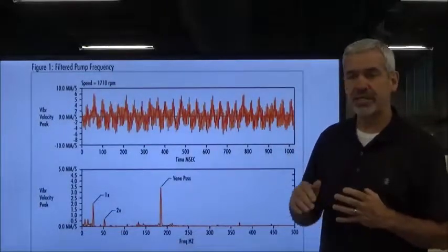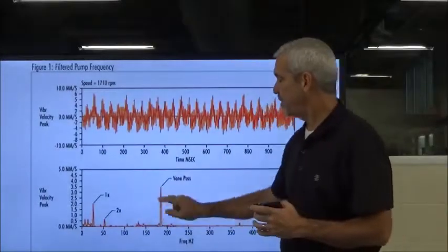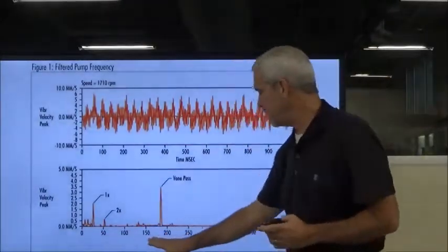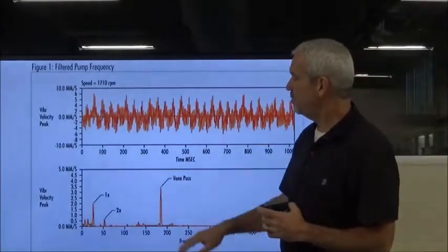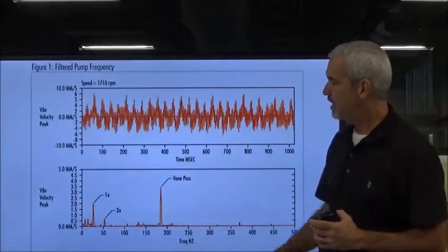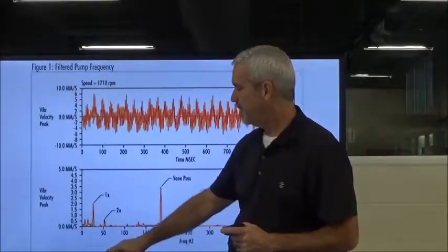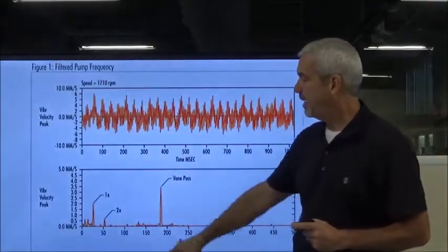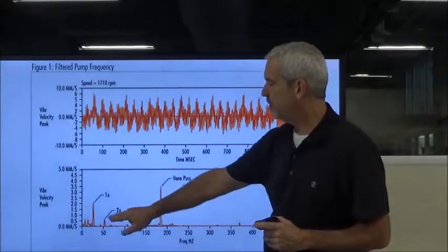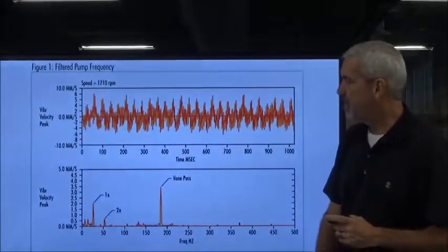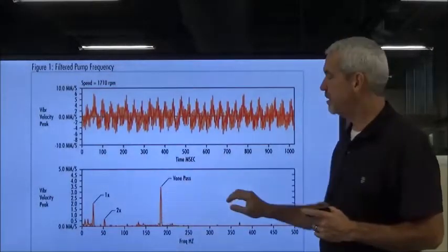That's basically the spikes that we see along our spectrum, not spike energy, but these spikes within this spectrum. And down below is the frequency at which the vibration is occurring. So this is translated to an FFT down below. This is our 1 times RPM, or cycles per minute here. And this is 1 times, so we've got a little bit of imbalance probably going on here. I'm not sure what the 2 times is there. Could be misalignment.